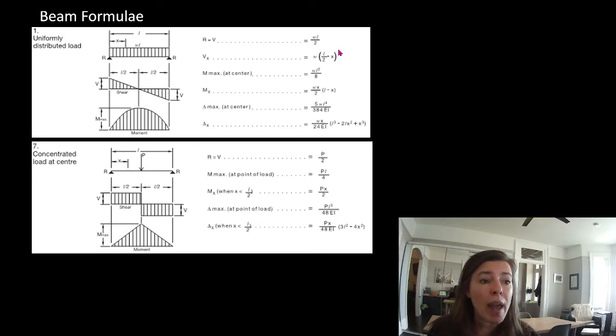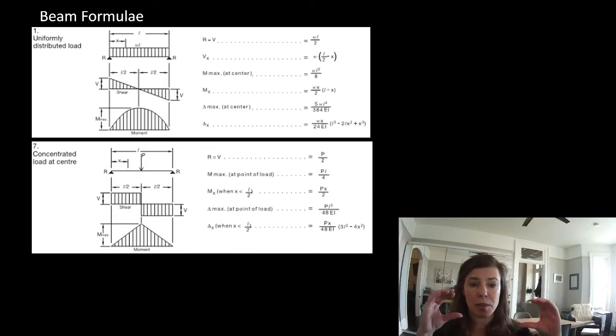Well, the same way we're going to compare this to the actual reduced shear value or the actual reduced capacity of shear for our beam and the actual reduced capacity for moment on our beam, we will use this to help compare against the allowable deflection. And those three things next year will let us say, this here is a beam that meets all of the life safety requirements, all of the stability requirements, and all of the stiffness requirements we've set out for ourselves.